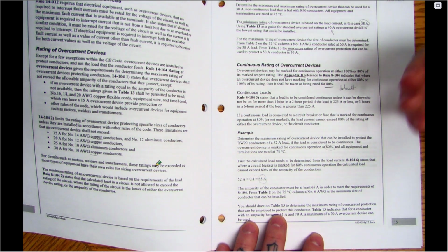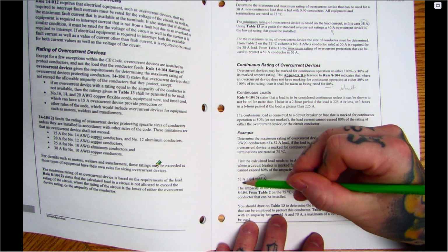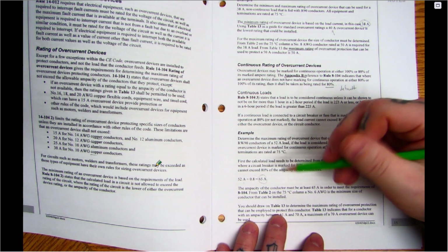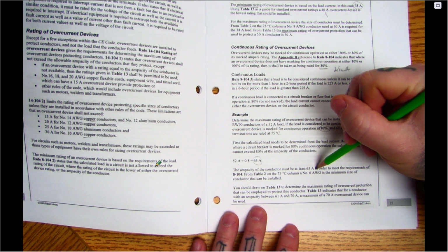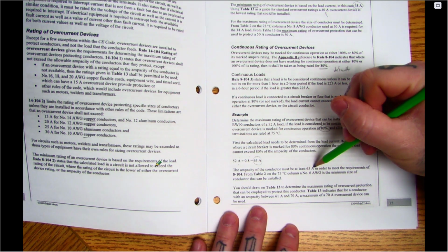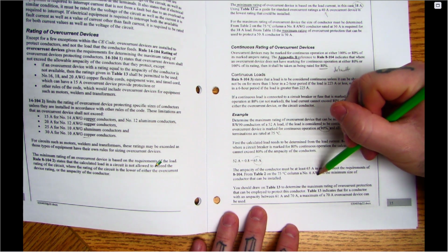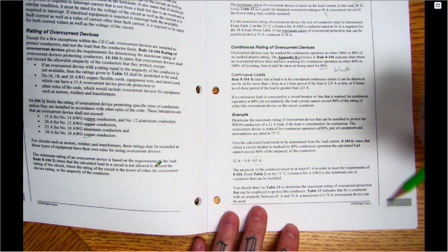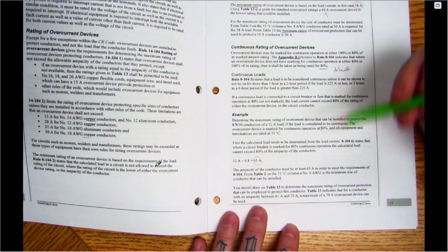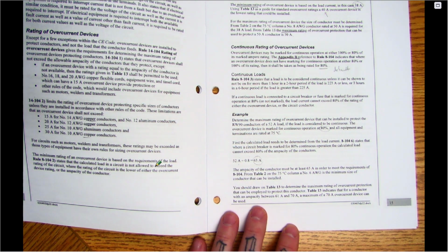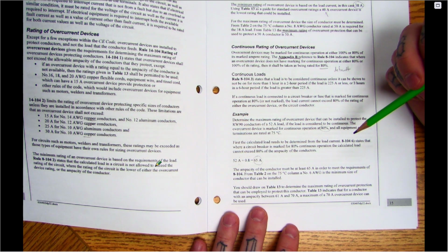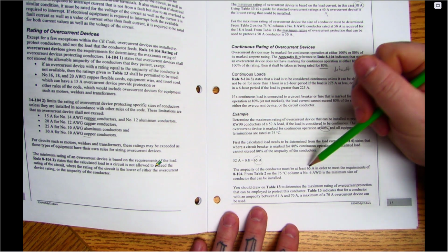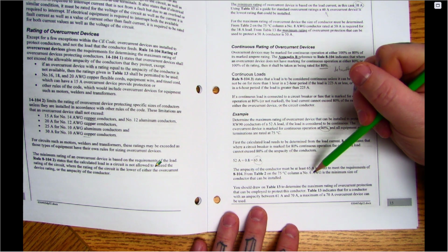Again, it's not that the load is going to draw this, it's going to draw 52 amps, but it's going to do it for a long period of time. So if we inflate that ampacity prior to going to Table 2, then we use that new inflated ampacity to size our conductor. Then we know that even though that load is going to be on for quite some time, it's not going to get as hot because we've basically upsized the conductor to account for that. Okay, so then it says for 65 amps, you're going to use a number 6.